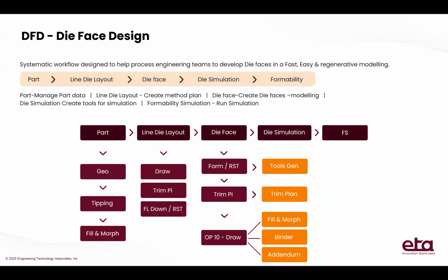Also, we do support carrying over these surfaces or geometries you generated to the FS module, which allows the user to run a more detailed simulation, like adding the guide pin, defining a specific binder force, using a line bead, virtual bead, or geometry bead. If they cannot do it in the DFD, they can do it later in the formability simulation module.